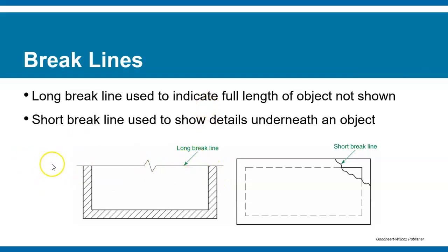This long break line is like saying, I'm only showing you from the side of one side of this line. See how it's got an arrow pointing down and an arrow pointing up? It's saying there's stuff on this side, but I'm not showing it to you. I'm only showing you the stuff on this side of this long break line. That's the way to understand that, okay? So that you focus your attention on these objects that are on this side of the long break line.